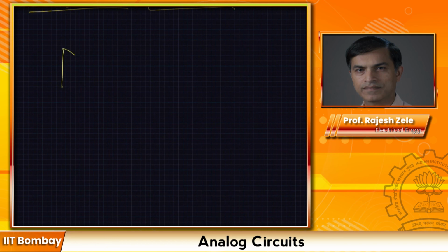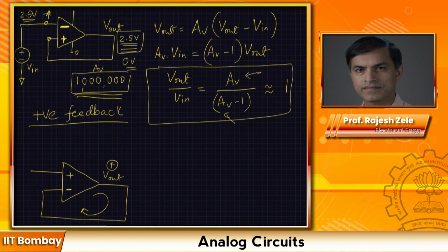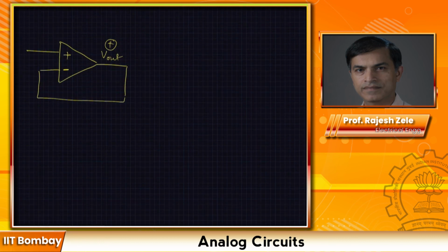Okay, so to have a negative feedback, you would draw the circuit in this fashion. The classic example would be something like this. So you have positive input, negative input, and this is again V out, which we call positive output. We need this to go over here. So we can see now we have a negative feedback in this particular loop. In the earlier case, if you look at that feedback loop, it's positive feedback, there is a positive sign. Here, if you look at this loop, there is a negative feedback.